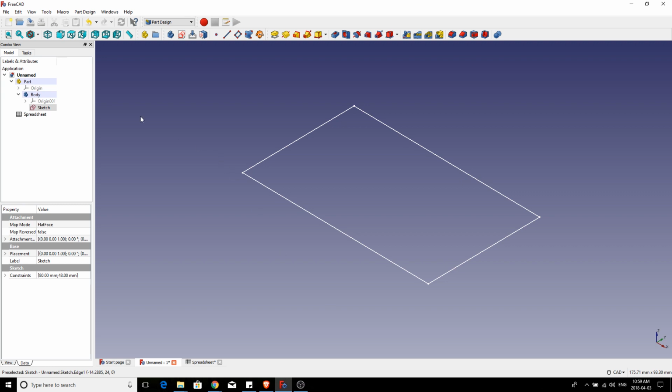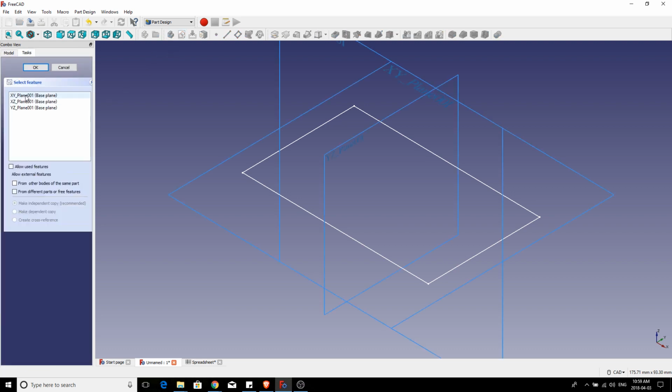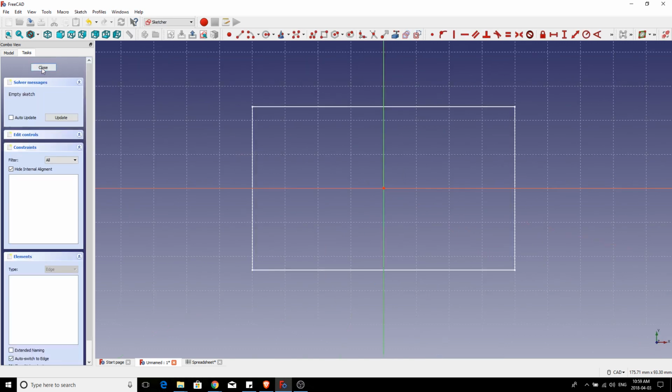All right, so let's get in there. First thing we're going to do is make sure that we're highlighted on the body because we're going to add a new sketch to this. So let's go ahead and hit that new sketch. We're going to use the XY plane like we did before. Boom, just like that. And what are we looking at here? Well, we are inside of a new sketch, but we can actually see the geometry of our old sketch, the credit card sketch that we did. Now, we aren't able to access that yet, but we are going to need the information about the width and height of this thing if we're going to build our model correctly in a parametric manner.